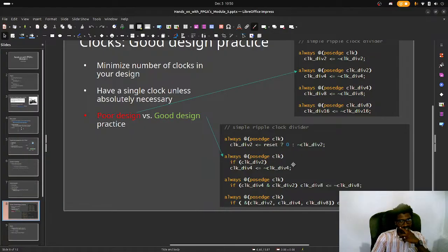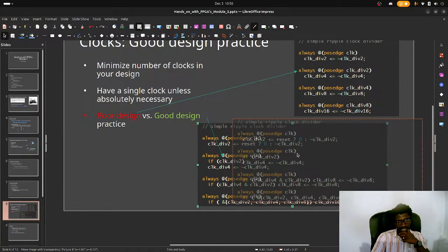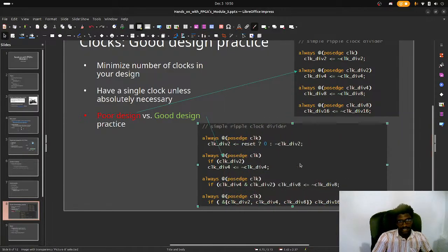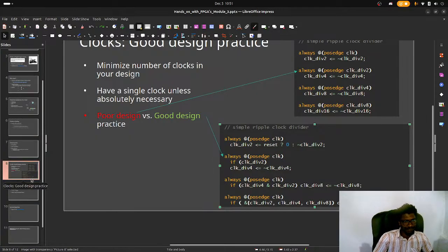If you're going to use a latch, set it explicitly, then use the assign latch, and then these are all basically being oscillated based on the beginning clock. And here the beginning clock has an implied latch, and here it doesn't have an implied or inferred latch, and that is basically what makes a bad design.